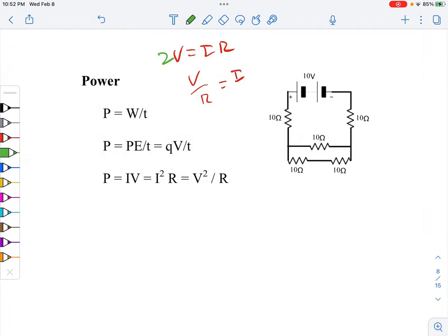The problem with this is if you double the voltage, then for a circuit that has the same resistance, you wind up doubling the overall current too. So you wind up with 2 times 2, so you get 4 times the power. How can this be? Well, doubling the voltage has the effect of doubling the current. So like, look, 2 squared is 4. I know my handwriting is really pretty, but you know how to do 2 squared. If you triple the voltage, you triple the current, you get 9 times the power. So that's one thing to watch out for.